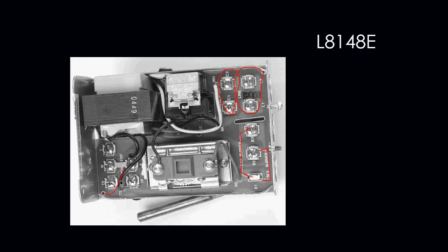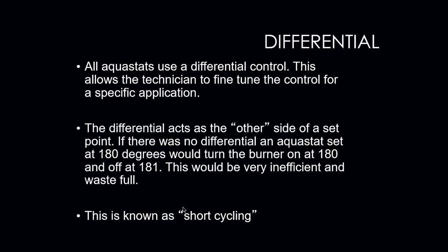Up here is our thermostat wiring, and for actually zoning, we may actually be able to wire a zone panel to this. Here is your transformer. Here's your relay. Here's your bellow right here. There's your sensing element right there. Okay, this guy sits inside the boiler, inside what we call a well, and that's how this guy is actually able to sense the boiler temperature.